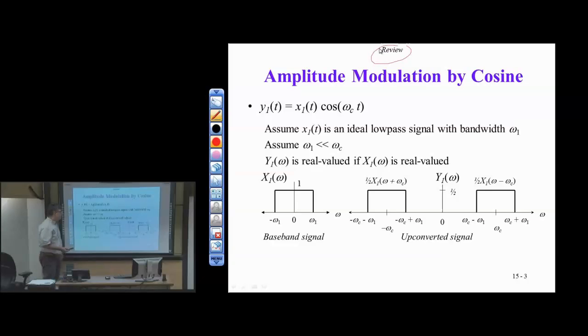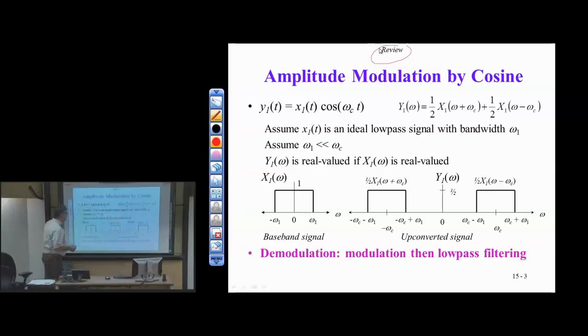All right, so we're going to have two channels in QAM. We're going to have one channel of PAM that's upconverted and another channel of PAM that's upconverted. So the first channel of PAM is going to be upconverted according to the cosine. This X1 is going to be a baseband signal. In practice, this is going to be a baseband PAM. It's going to be pulse-shaped, and we'll have some amplitude scaling based on the bits we want to send. And we're going to modulate by cosine at low frequency. This is the first stage. This is the baseband QAM side.